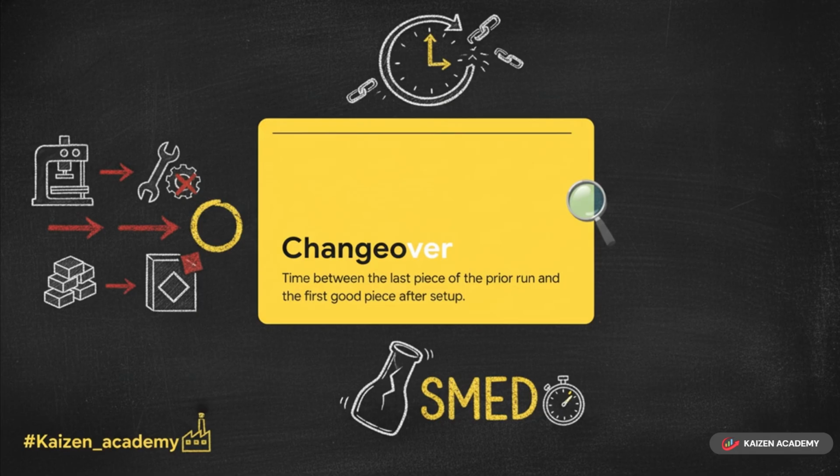A changeover is not just the time it takes to unbolt a tool and bolt a new one in. It's the total elapsed time between the absolutely last good piece of the previous run and the very first good piece of the new run. That means all the tiny adjustments, the test runs, the tinkering, the defects, that all counts as changeover time. And that is the ultimate enemy of efficiency.